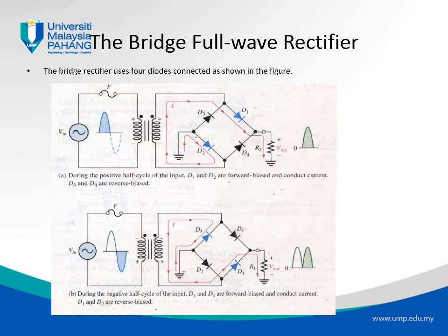The second type of full wave rectifier is what we call the bridge rectifier. So what is a bridge rectifier? In comparison, a center tap rectifier requires us to tap the voltage in the middle of the transformer to separate it into two parts, right? Half and half, to divide the output voltage into half. Instead of tapping into the transformer, which is finely coiled, a better and more commonly used way is this type of bridge rectifier.